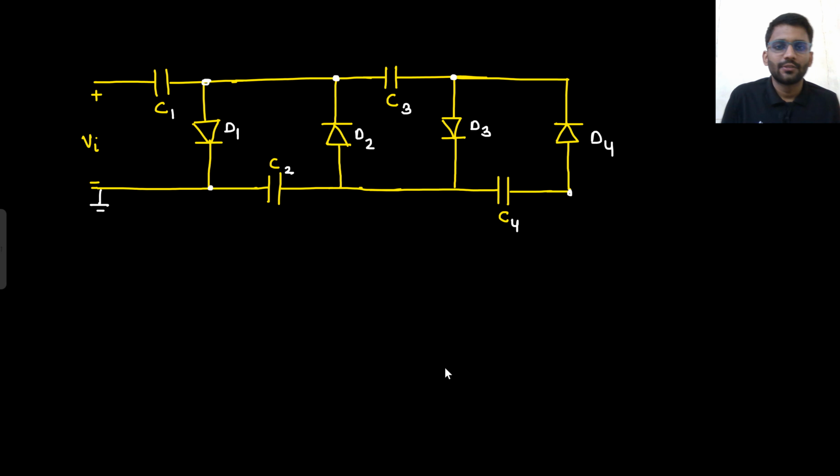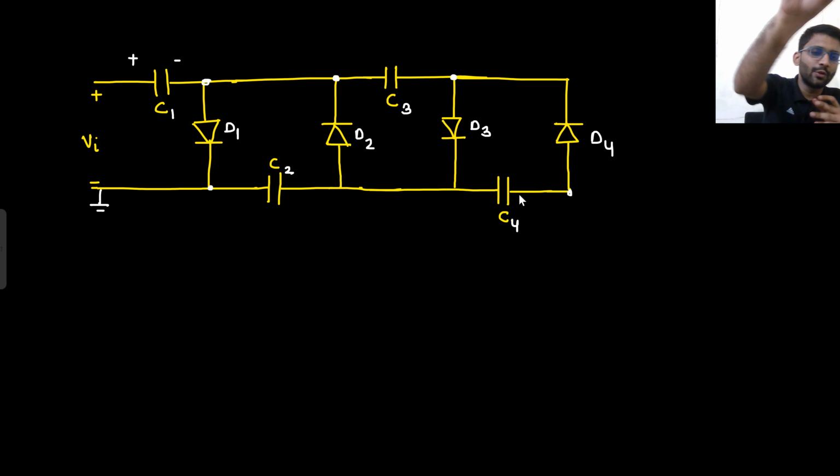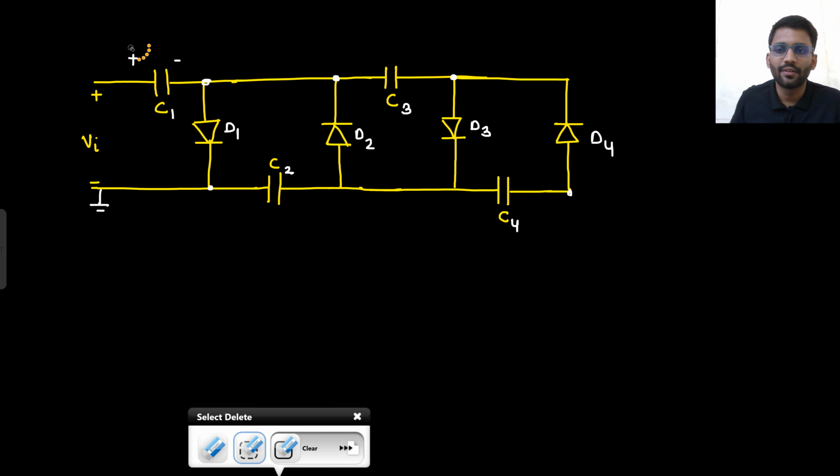Okay. So look, one thing we already know: here Vm would come and here 2 Vm, 2 Vm, 2 Vm. This is what we can remember for a standard circuit. You can remember that the first capacitor will be charged to Vm, the rest will be charged to 2 Vm. Now you don't know the direction. How will you know the direction? By the diode. Very easy.